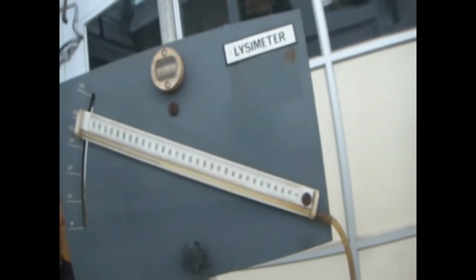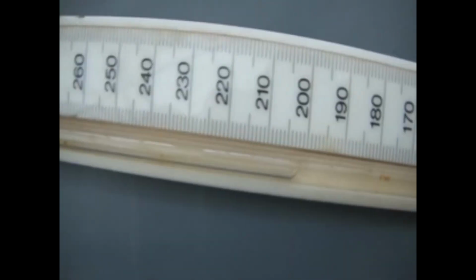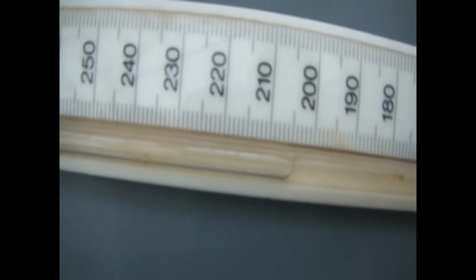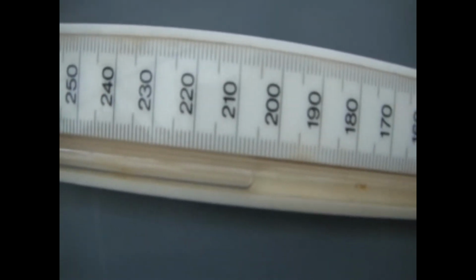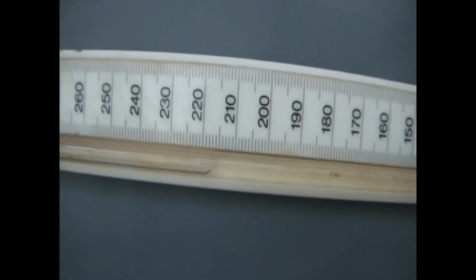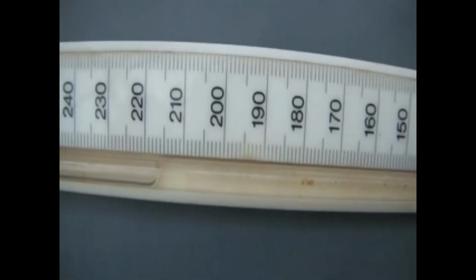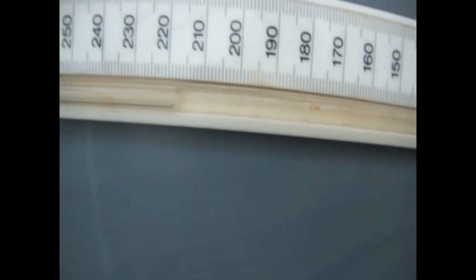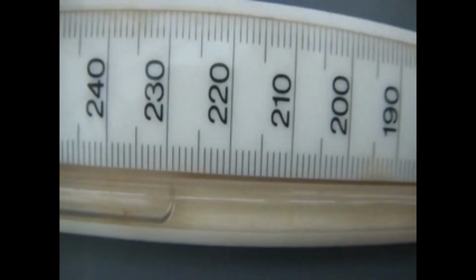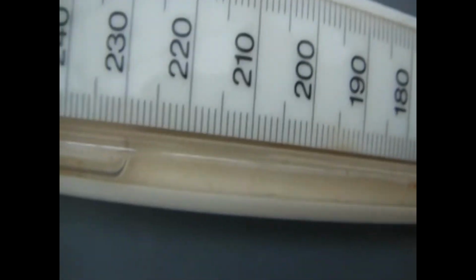So now you can compare between 15 degree and 25 degree. Its sensitivity is reduced now because fewer divisions have moved for the same 2 kg weight. So I am adding one more weight. It is 2200 grams. It is reaching 205. One more weight, 2400 grams, it is reaching 215. One more weight, it is now reaching 229.